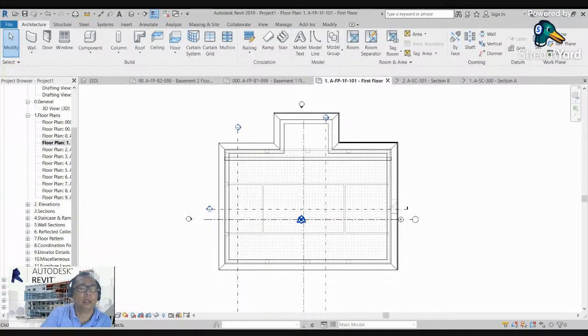That's why in Revit you need to segregate that, because if you do not, you will split it in every room, even though they are the same type of wall. For example, you use 200 millimeter on external and 150 millimeter on internal, and then you place the finishing of ceramic tiles. How about if in a room, for example the bedroom, you are not using the ceramic tiles, but you created a 150 wall with the attached double wall of ceramic tiles, the finishes?